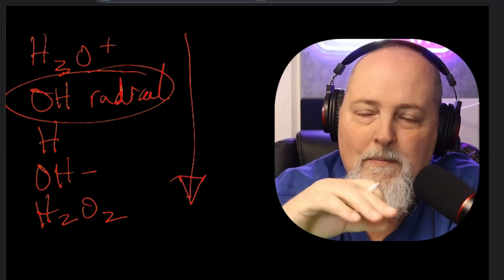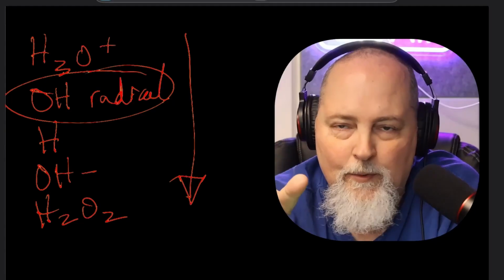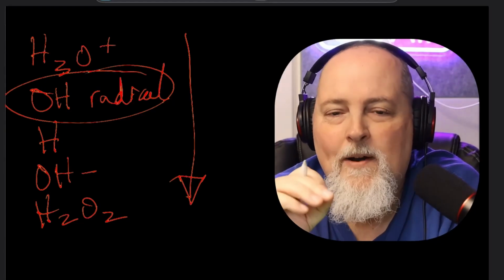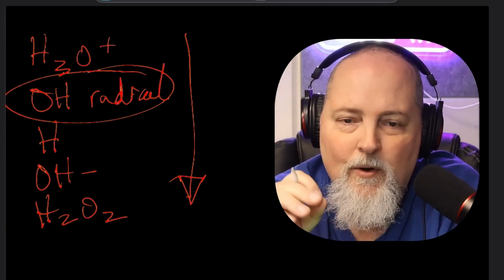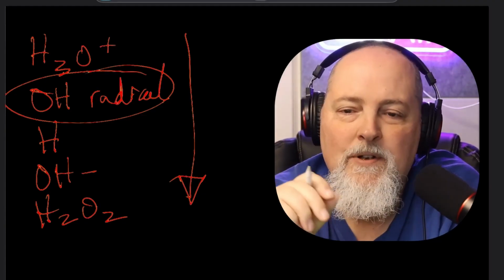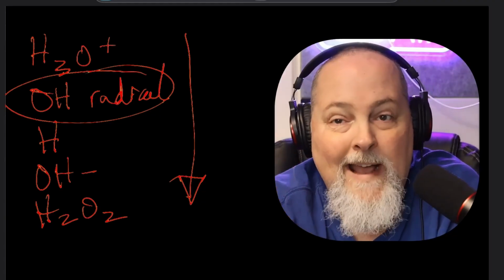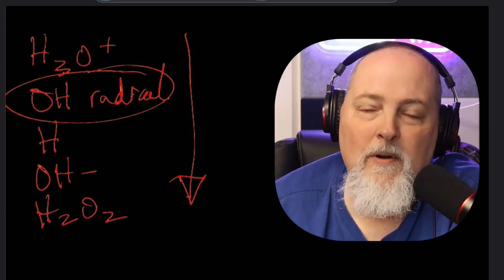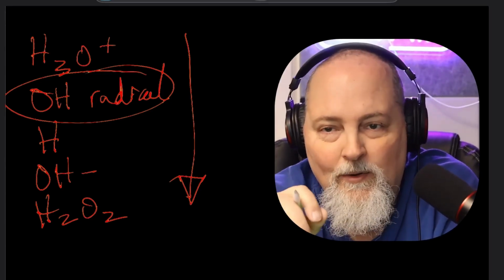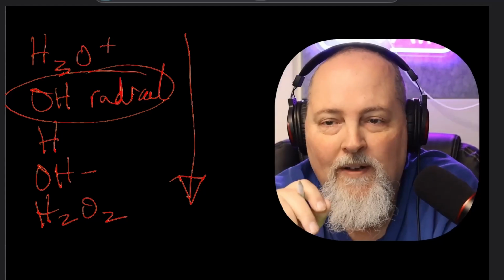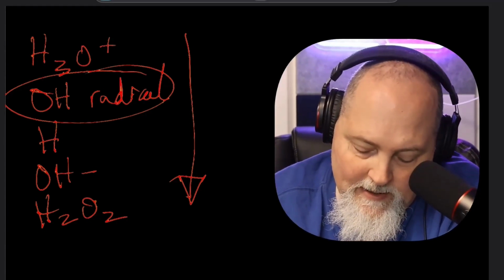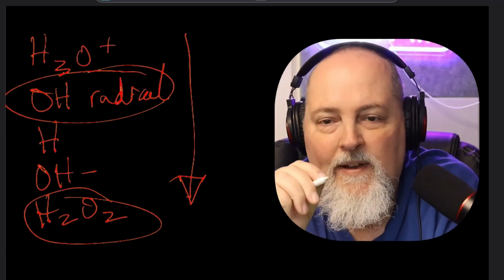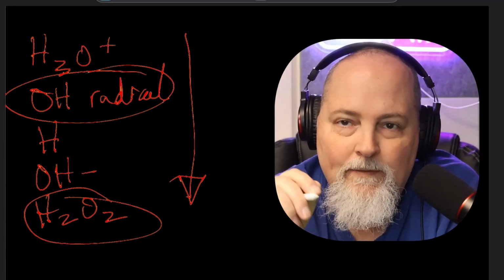It produces hydrogen peroxide, it produces these other reactive oxygen species, and all those things matter because the oxygen and the peroxide increase corrosion risk, and hydrogen plus oxygen can create gas management issues. So one reaction worth remembering is that hydroxyl radicals can combine to form hydrogen peroxide. Hydrogen peroxide is an oxidizer. That means it can make the coolant more aggressive towards materials.